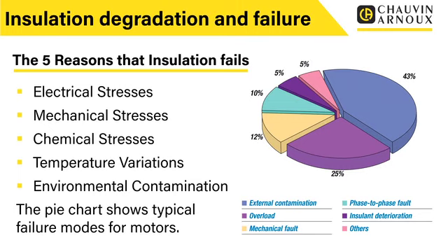So again, there are a lot of reasons why insulation can fail. And obviously, common sense dictates that keeping your motor dust-free, dry, clean, away from any oils or contaminants or coolants and things like that is good practice if you want to see your insulation last and give a long life for your motor. So again, in any preventative maintenance system, we try to keep away from that.